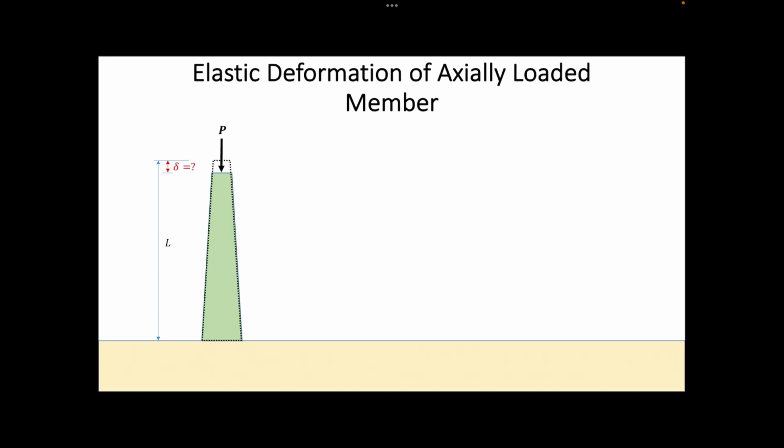First, we know that displacement or deformation can be found from strain. Second, we know the strain can be found from the stress and the modulus of elasticity using Hooke's law. Third, we also know that if we can find the displacement for a differential length of the column, we will be able to apply an integral to find the displacement for the entire column. That being said, let us consider a differential length element, dl, of the column as shown on the screen. Then, to find the average normal stress for this element, we can consider the equilibrium of the portion of the column on top of it.